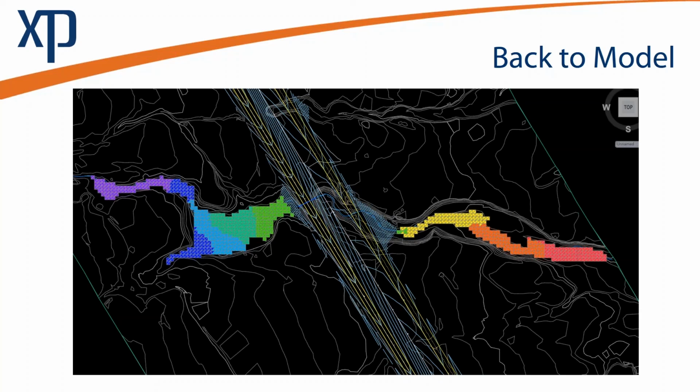Okay. You can always import this directly into a regular tin surface. A tin, this ASC file can be added to a tin surface. You'll get all the same triangles within here, but you won't get the boundary elements. So you'll have to do some trimming of the tins so that it doesn't cross the road here and any of the bends and things like that. You'll have to do some cleanup if you use a DEM within a regular Civil 3D tin.